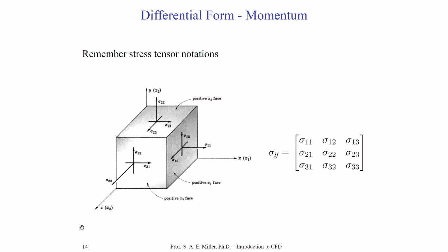So here we have 3 axes, the x, y, and z axis. And our fluid parcel, or volume in this case, I'll use these terms interchangeably, is located at the origin. And it has some small differential elements. On each of the faces, we might model the particular forces. This little value, sigma 1, 1, would be represented in this tensor. This is not a matrix. It is in fact a tensor, and that is because it has certain properties when rotated. Matrices do not have these particular properties. So remember to reference this as the stress tensor and not the stress matrix.